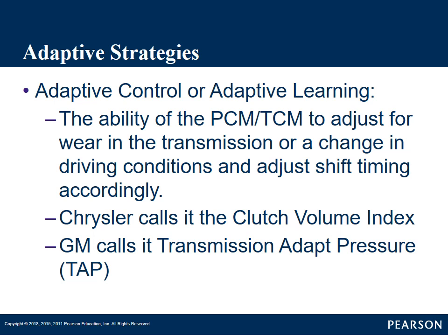If you didn't, the transmission shifted improperly, and even a brand new transmission, if you didn't reset those clutch volume indexes, you could burn up or ruin it.